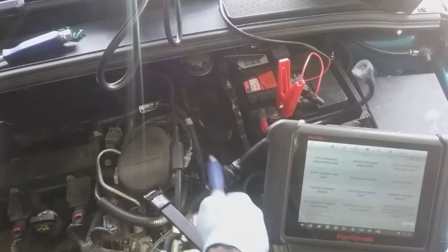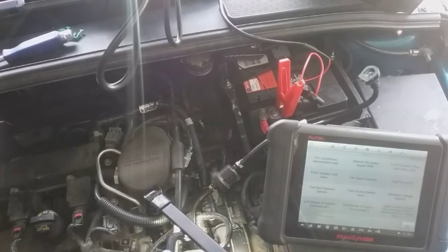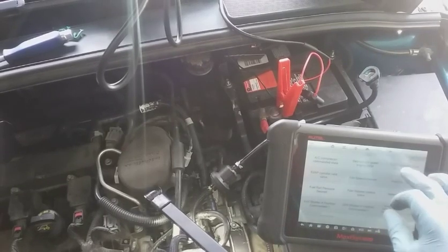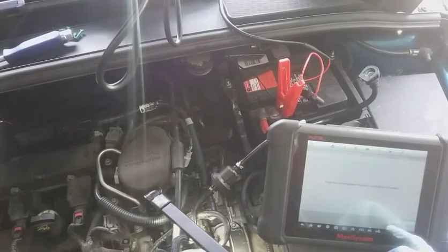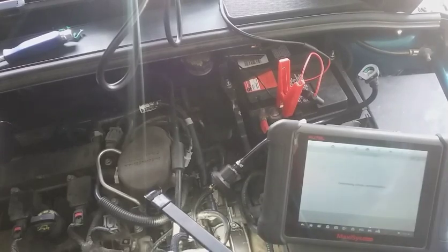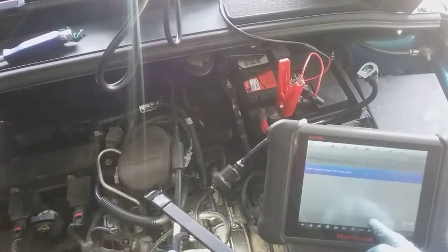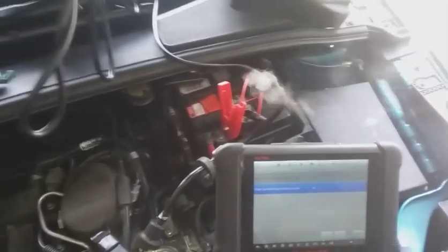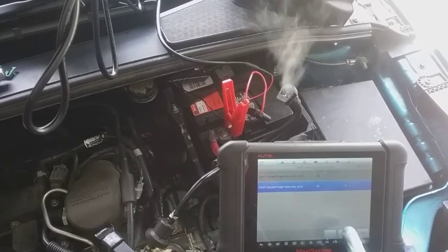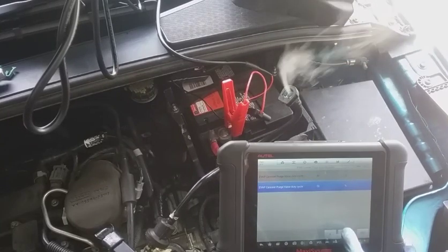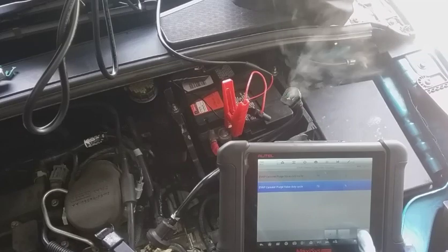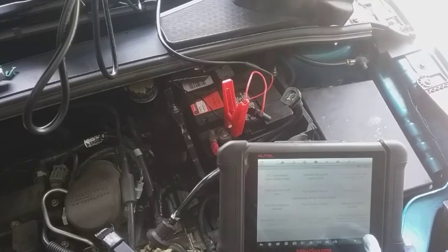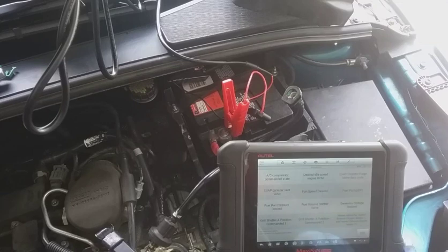Sometimes what could happen is this solenoid could just go out because it gets stuck in a particular position, because it's constantly activating thousands and thousands of times through the course of the day. Sorry, I didn't know it was off the screen there. See, it's stuck right there. I'm going to cut it all the way off, see what happens. Okay, it closed. I felt it close in.